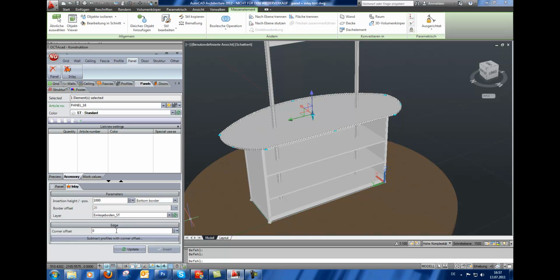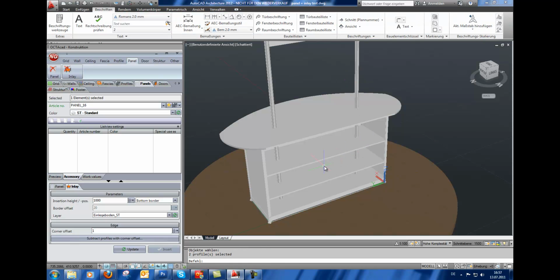We select the tabletop, then we can give an offset. It's the distance between the extrusions. Like in this case I will set 1 millimeter, and then I have only to click on the button here, and then I can select the 2 profiles, 1, 2, and by tapping on enter it's done.